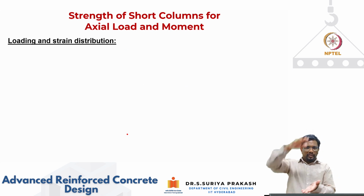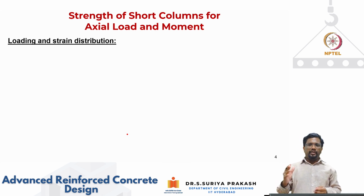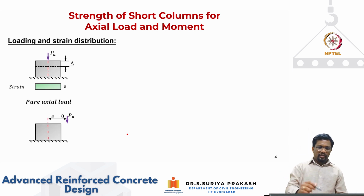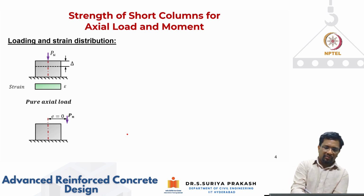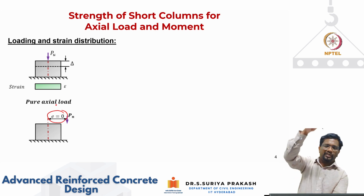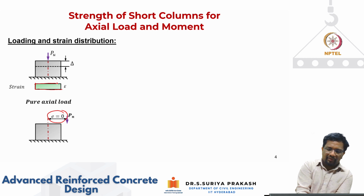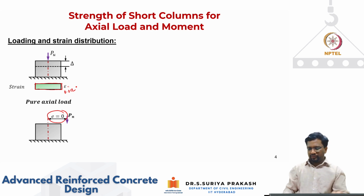For pure compression, we know that the entire cross section is subjected to the same level of compressive strain. As per IS 456, we have seen that the failure strain should be considered as 0.002 for pure axial compression. When the column is subjected to pure axial compression, the eccentricity is 0. That means the load is applied exactly at the CG of the cross section, and the entire cross section is subjected to the same level of axial compression. So we take this value to be 0.002 as per IS code.